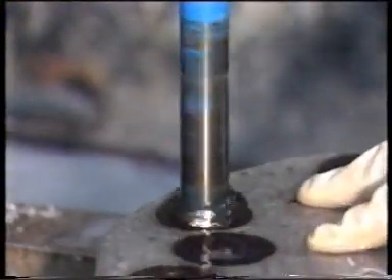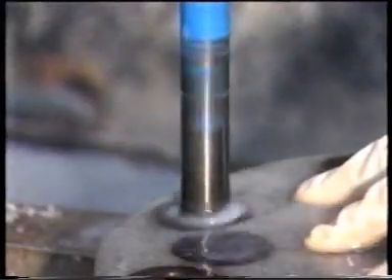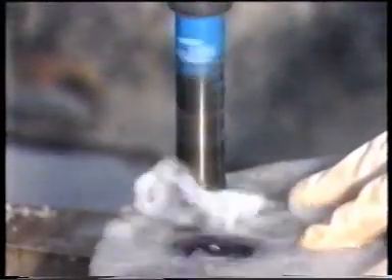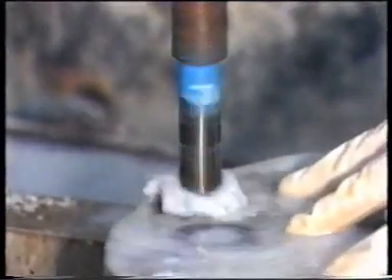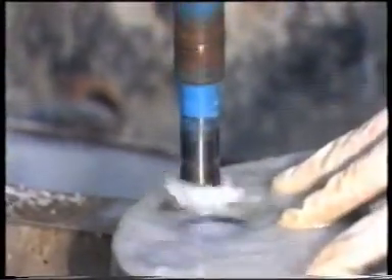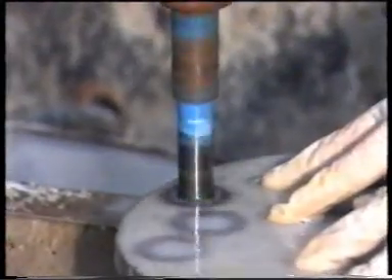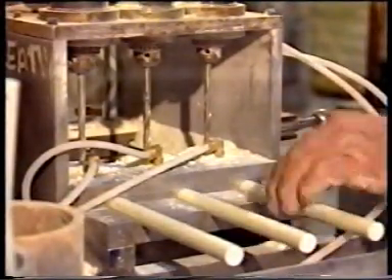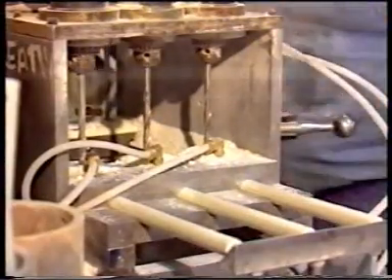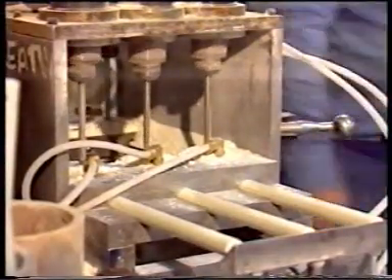Although high-speed steel tools can suffice, tungsten carbide and diamond tip tools are often preferred. Also, coolant is often recommended to minimize heat buildup and to prolong tool life. Work-holding fixtures should provide proper part backup to prevent backside material breakout in various operations.